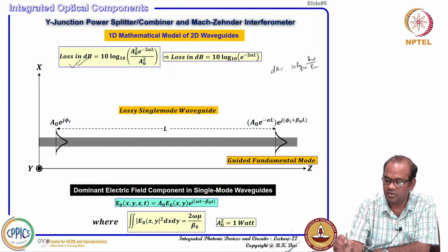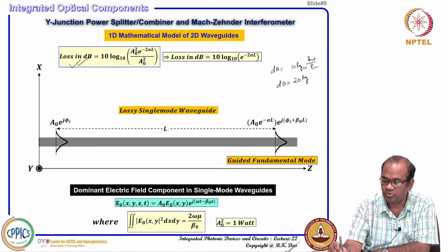That is actually decibel power. And if it is voltage, the same dB will be written as 20 log of V out by V input, since V square by R equals power from the circuit point of view.